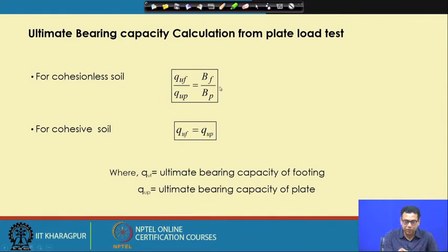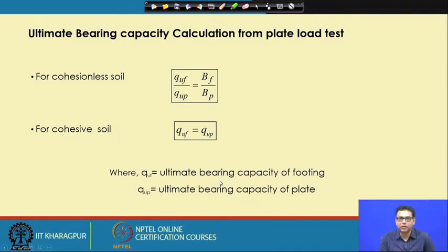But for cohesive soil, as I have already mentioned, the net ultimate load is not a function of width; even the ultimate load is a function of depth only, not of width. So, in none of the cases, whether ultimate load or net ultimate, does the bearing capacity for clay soil depend on the width of the footing. So, that is why the width is not giving any effect.